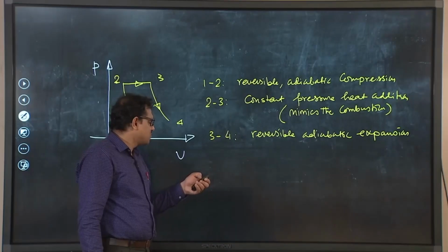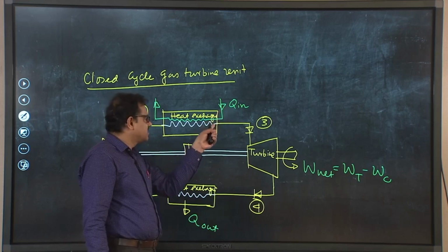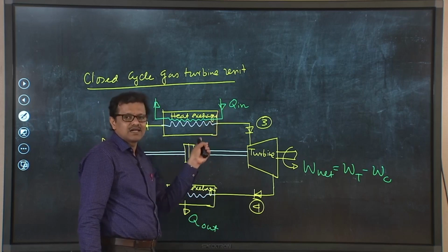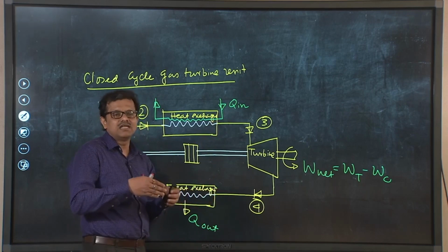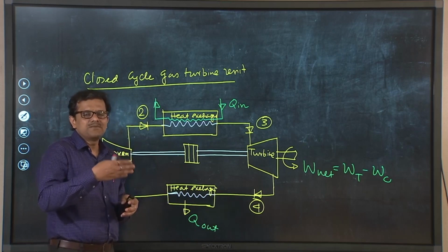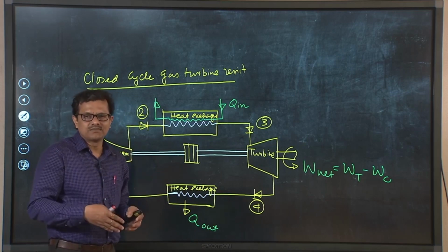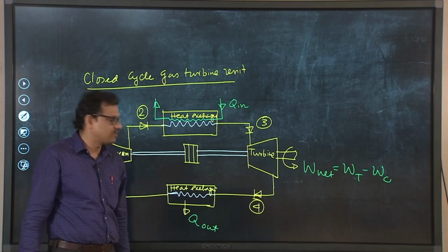So, here also we are assuming that the heat added to the working fluid in the primary circuit is at constant pressure and Cp, essentially because in a combustion process, as I said, the Cp of the gas will change in the combustion chamber. So, it is advisable to consider the average value of Cp and gamma.